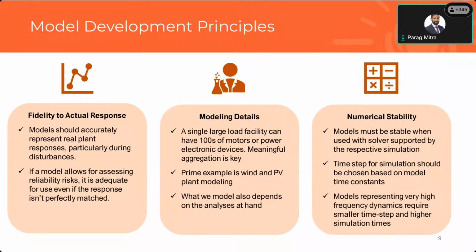We need to be very careful about how we are coding these models, because certain coding styles or practices can lend to being more numerically unstable than others. So follow good modeling practices. We have some guidance on those in the document as well. But the idea is to make sure that we are able to distinguish between a solver-driven problem versus an actual system problem. So let's go to the next slide here.